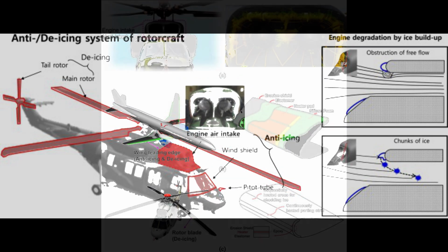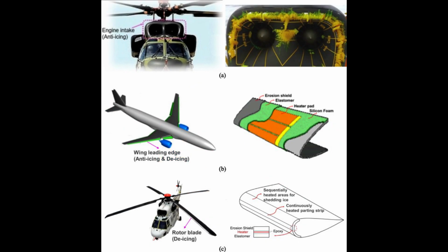Airframe anti-ice. Airframe and rotor anti-icing may be found on some larger helicopters, but it is not common due to the complexity, expense, and weight of such systems. The leading edges of rotors may be heated with bleed air or electrical elements to prevent ice formation. Balance and control problems might arise if ice is allowed to form unevenly on the blades.